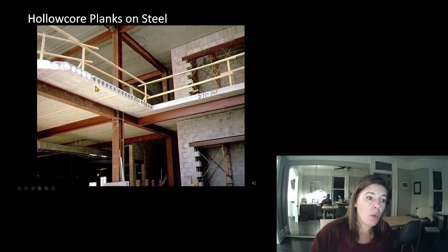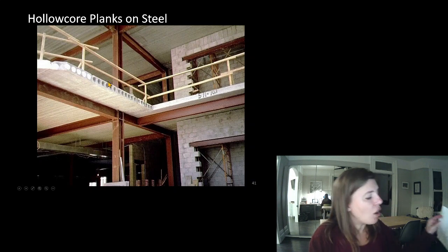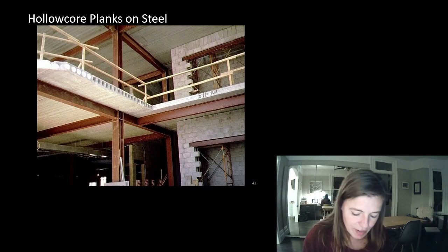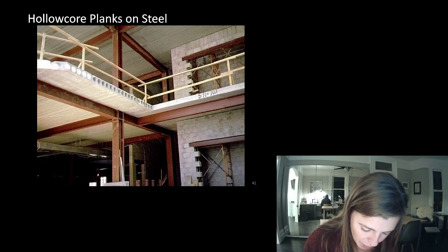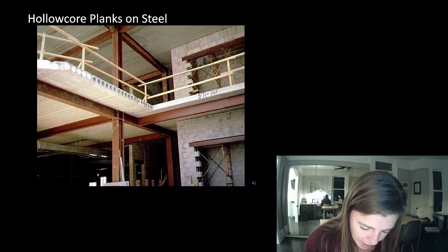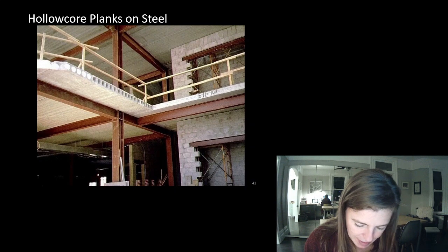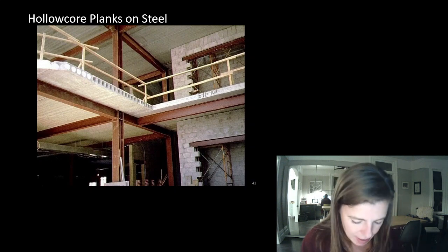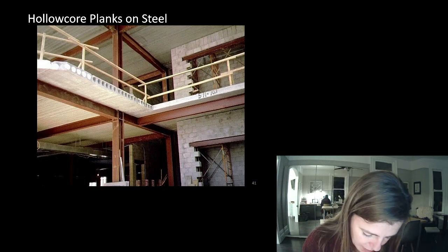So now this is more like we've got a series of joists spanning in this direction. So I often think of hollow core as a series of little concrete beams with kind of a topping on it doing all the work. So this is our core. We've got a bit that's the topping, and then we've got bits that are funny little beams, and I'll show you this in just a second.